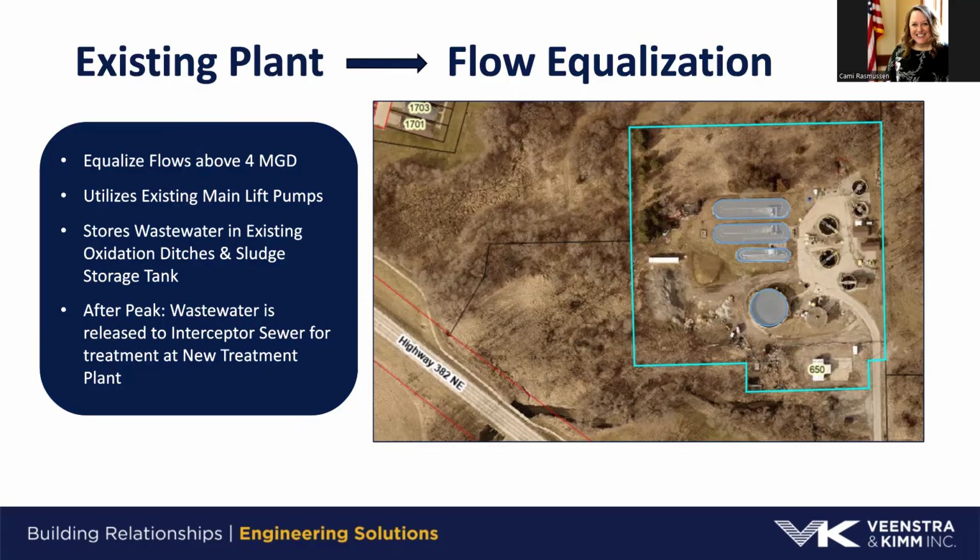From a storage standpoint, if you're storing wastewater in there, is there anything we would need to be concerned about as far as like odors, things like that could disrupt? Generally, in this situation, if we're looking at it from a peak shaving standpoint, that's fairly dilute. We're getting the peak because of influence from surface water and groundwater. So we're sending flow there that's only going to be there for a short period of time. That peak passes and we can return that flow hopefully within a couple of days. So it's very short duration and it should be diluted.